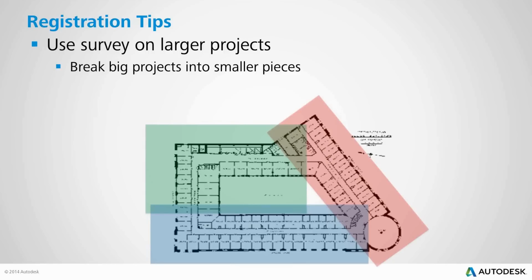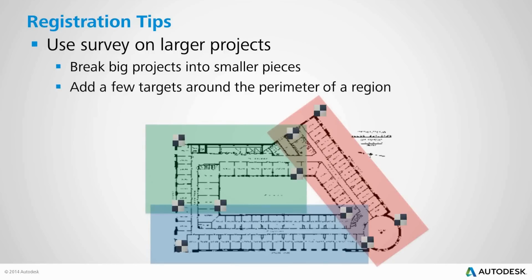Then you can introduce a handful of targets in each of these areas and around the perimeters of those regions, and use survey to bring these pieces in individually. So you can bring these individual projects together with that survey. This is sometimes a nice way to break up a bigger project to get better results.